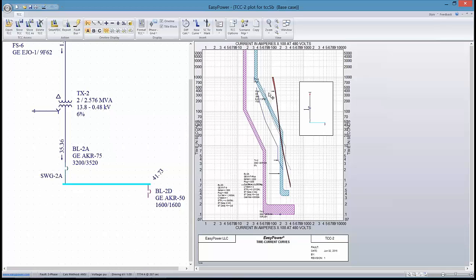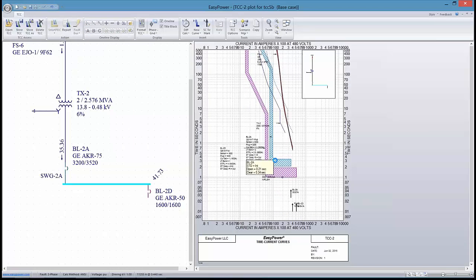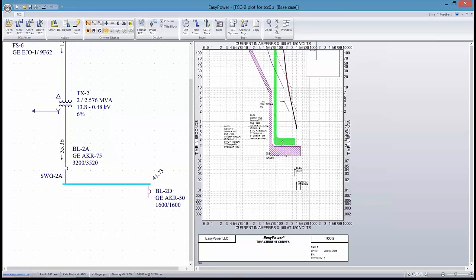We also have the transformer shown here, and clearly the way this is currently set, there's no protection from either the fuse or this breaker for the transformer. So based upon what other requirements we have, we might want to make some adjustments, and show our voltage fault arcing current for this breaker.